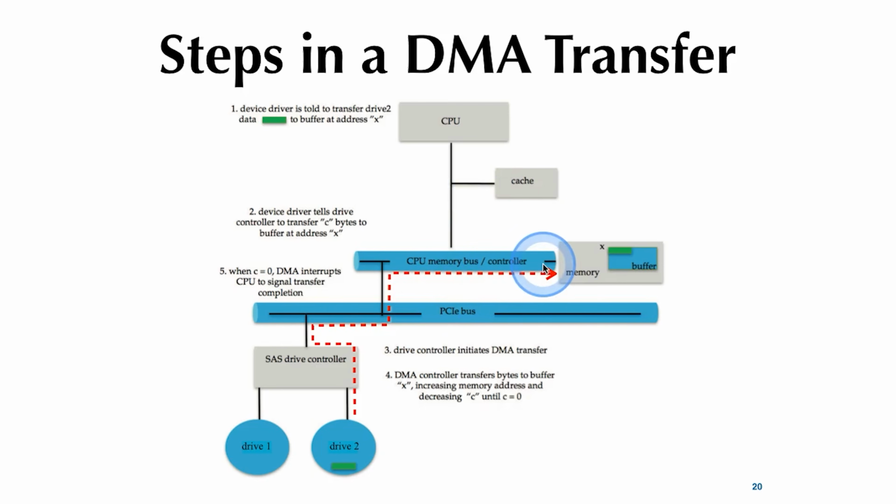And it does need to be aware of memory, so it could be on the CPU memory bus controller here, and it works with the drive controller. These drive controllers, depending on the access mode, could stream data, but what actually deposits into the memory would be the DMA controller rather than the drive controller.